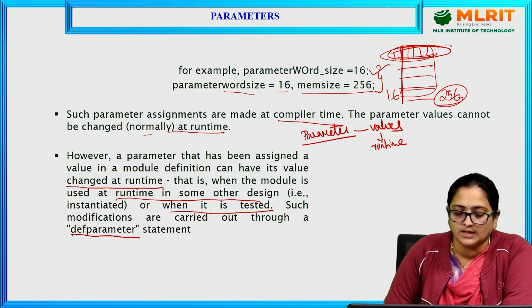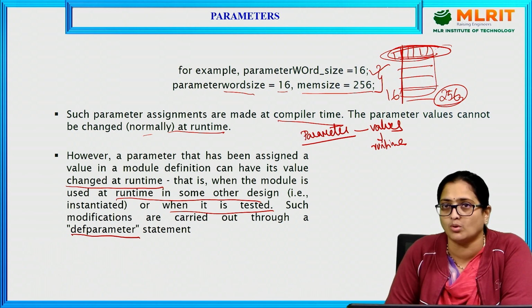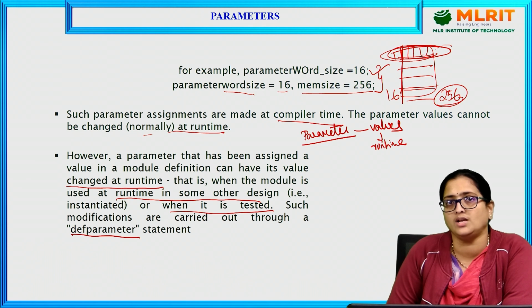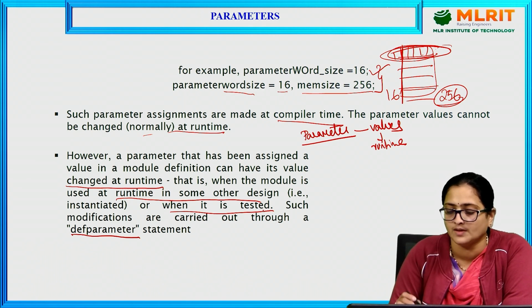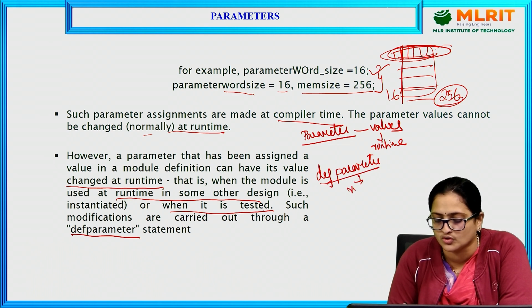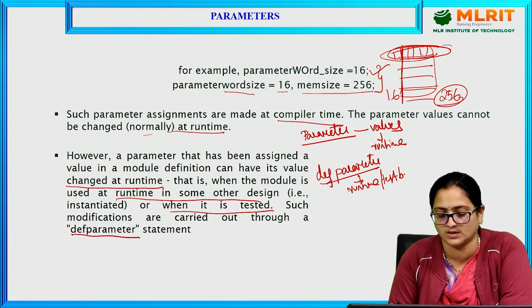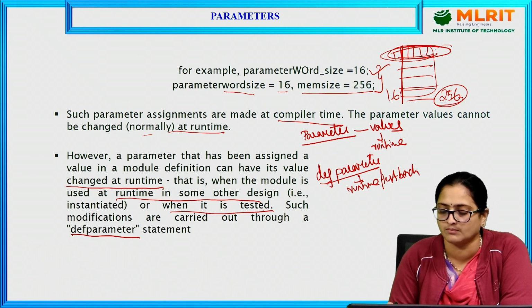But in certain cases, when you are assigning parameter values in your module, those values can be changed at runtime or at testing time by using the keyword defparameter. So here you can change the values in your test code.